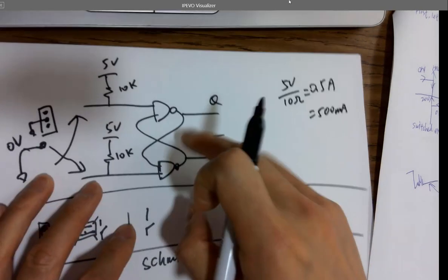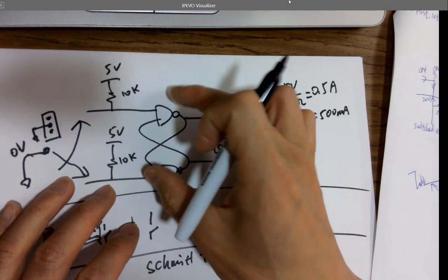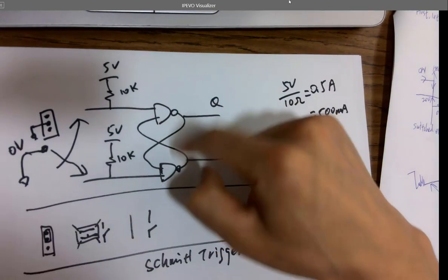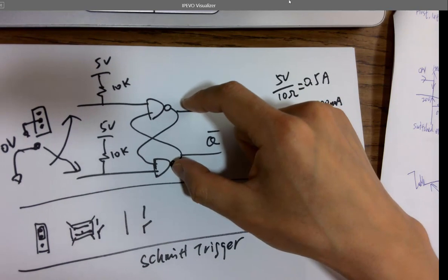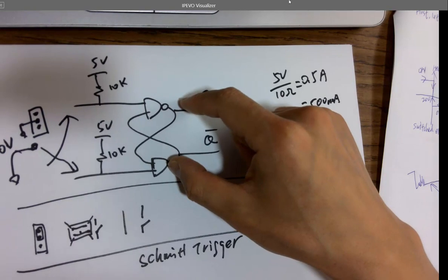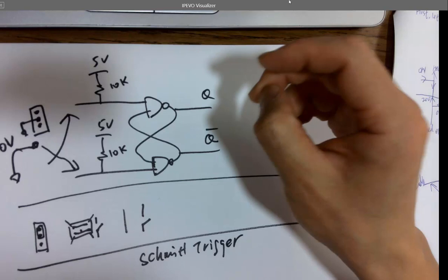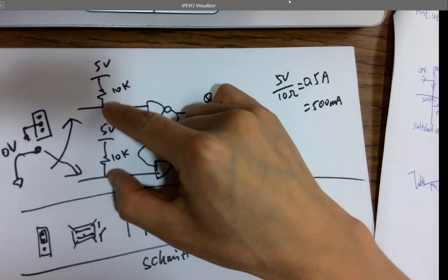But anyway, before we go into there, if you are building a debounce circuit on the breadboard using one of these techniques for one of the projects maybe happening towards the end of the semester, are they synthesized NAND gates, or IC chips that I can find in the lab? How would you build it on the breadboard? On the breadboard, they have to be discrete components. So you have to grab a little IC block which has an AND gate or NAND gate in there, and resistors as well. You are not able to do it on the FPGA because you have analog devices like resistors.